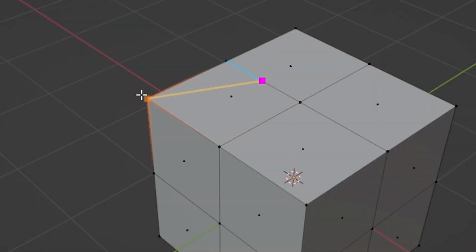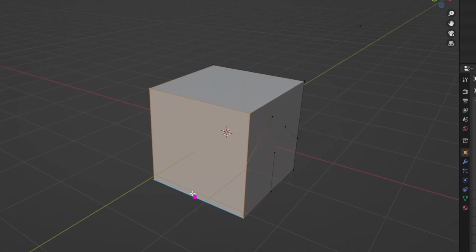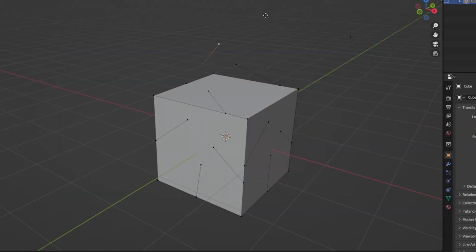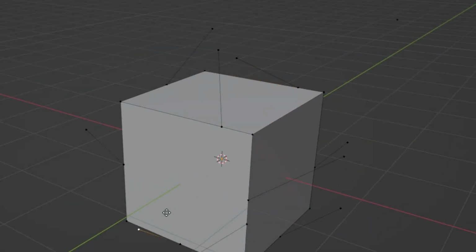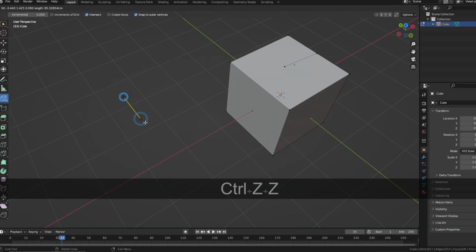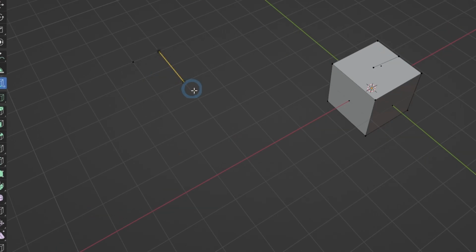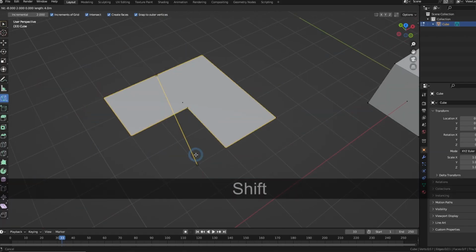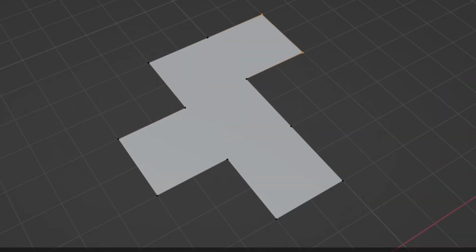It will automatically snap to vertices, edges, and even faces. If you stop cutting somewhere in the middle of a face without closing the cut, the vertex will actually stay there, but it will end up being read as some kind of separate segment. That said, if you're gonna use this for drawing separate segments, right after clicking the first point, you can type down your desired length for the second point. You can also choose to make it snap to increments of the grid. You can also automatically make faces if the drawn segments are closed, which kind of reminds me of SketchUp.